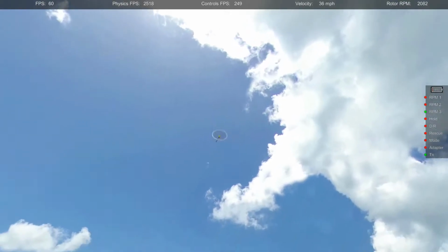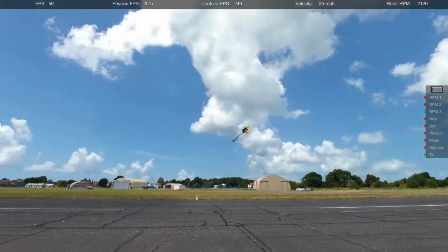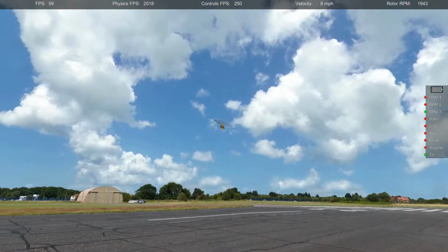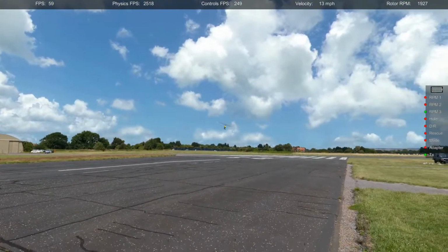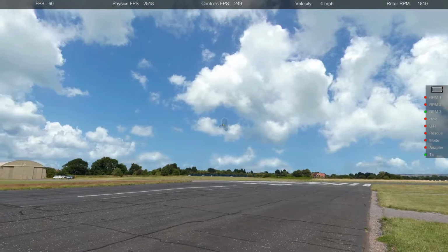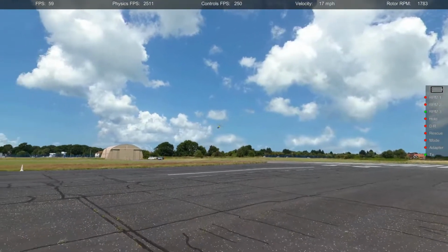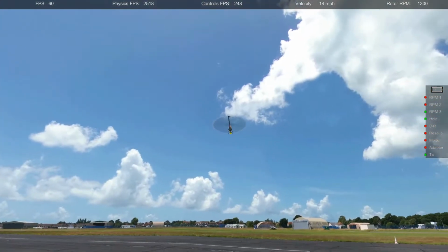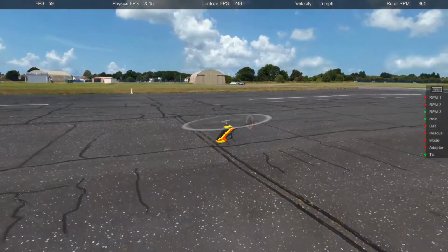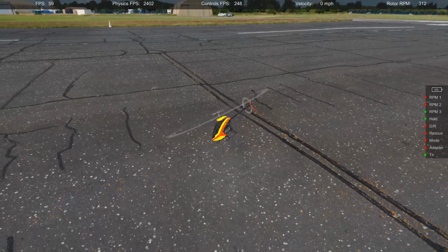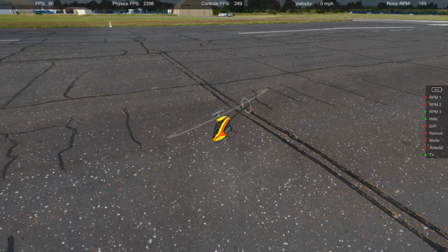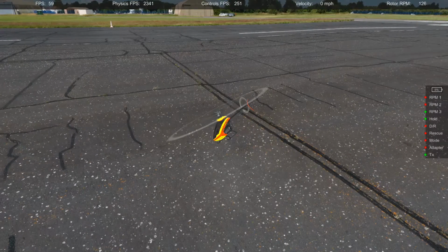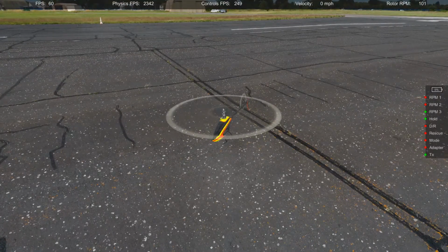So in 1902, October 26th, they take 2 photographs, both of them from the back, both of them of the glider in a bank. You'll notice that the left wing appears fat and that the right wing appears thin. This is their wing warping. And this is how they were able to bank the airplane. You'll notice they've added a vertical tail. The vertical tail actually is a rudder. It's coupled to the aileron.